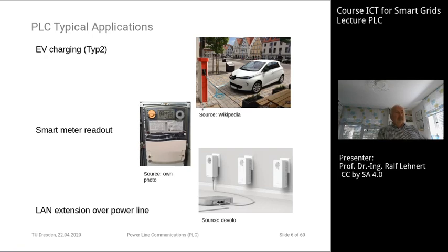The next step, and this is a step especially for our topic of smart grid communications: in many households we do now have electronic meters, not the old-fashioned Ferraris meters which are running disks, and these meters are quite capable. They cannot only simply count the kilowatt hours you have consumed, they can also be bidirectional if you have a photovoltaic generation on your rooftop and so on.